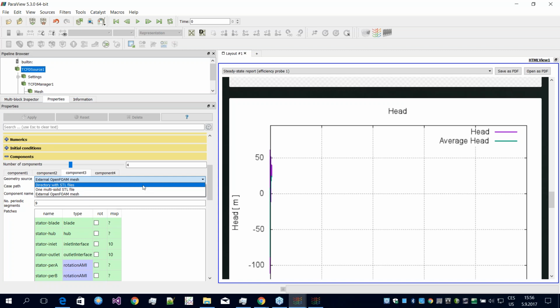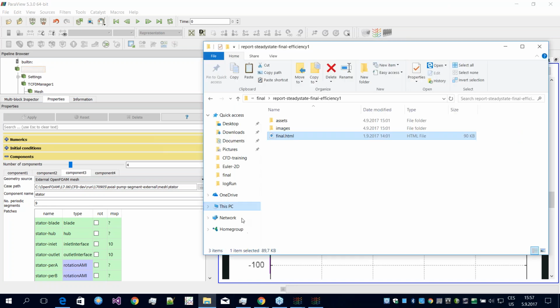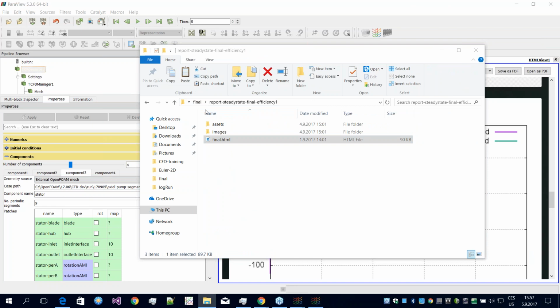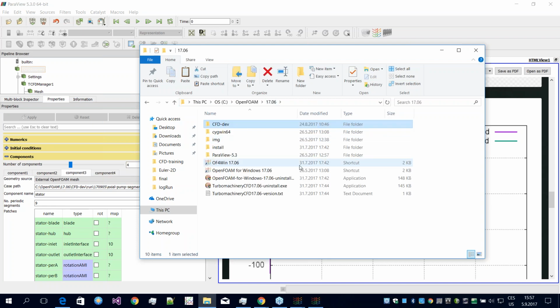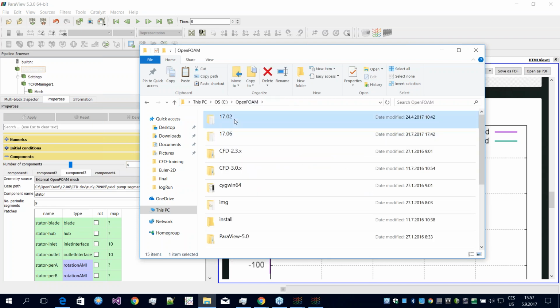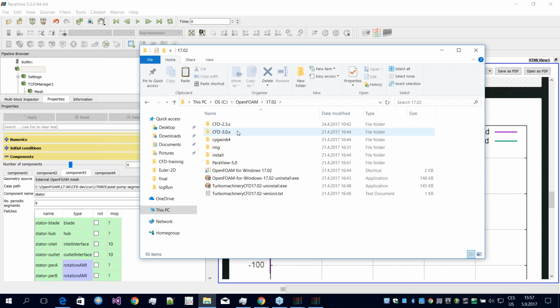Radek is showing it right now. You open the directory with STL files with the CAD data, so with surface format, of course STL, stereolithography format, and the workflow is very similar, a little bit different. Of course, we recommend it as a first choice, but some other clients ask if they can use their own external meshes for historical reasons.